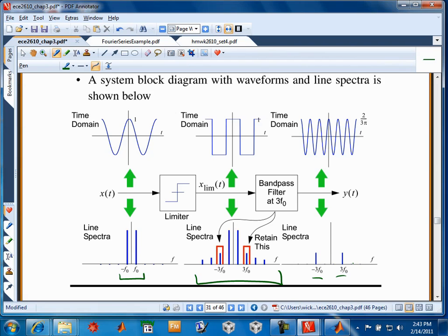So the rest of the elements on the back of that circuit I'm passing around constitute a bandpass filter built with inductors and capacitors. You see little brown shiny parts that are capacitors, and then tubular devices that have stripes or bands on them, which are not resistors but actually inductors. They're coils of wire around a ferrite core encapsulated in plastic. Most of you are familiar with the color code for resistors. There's a color code for inductors too.